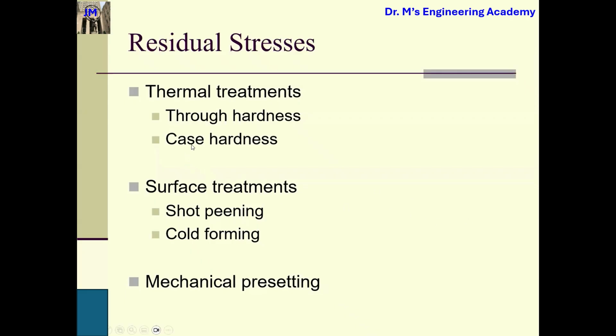Case hardening, you know case hardening, right? I told you guys, in case hardening we have a sealed chamber, and we put some liquid, gas, or solid materials that have smaller atoms in the chamber, and then we put the product that we want to heat treat in the chamber also, and then we seal the chamber.